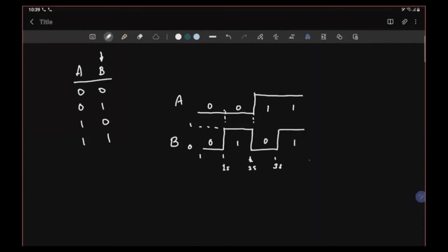So basically, these patterns give us the inputs of all the possibilities of A and B. And then the output of the gate will be F, and F will be whatever the outcome that you get from the output of the gate. Okay, so if you can set up the inputs as some sort of waveform that changes with time with these patterns, then we can display the truth table at the output.